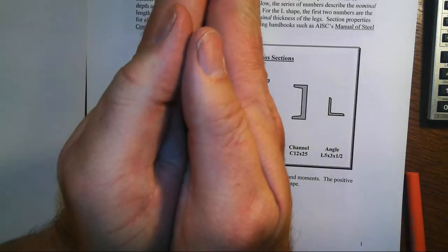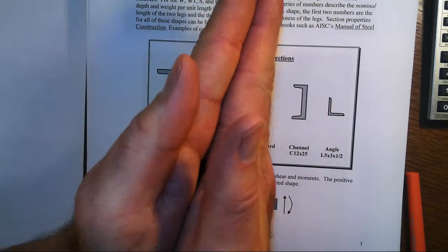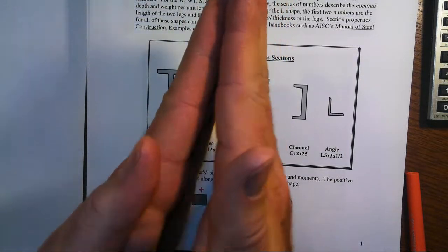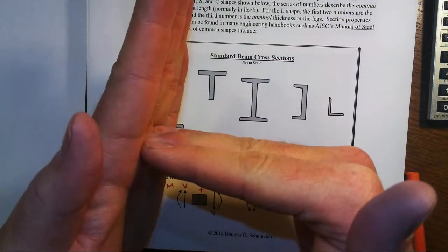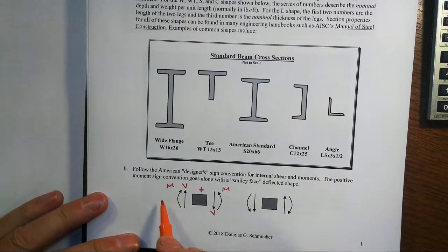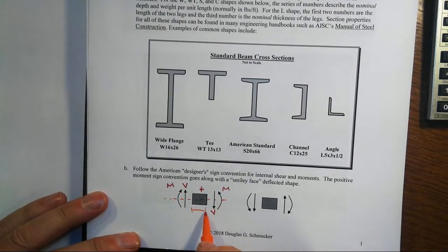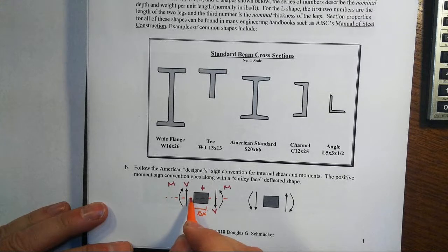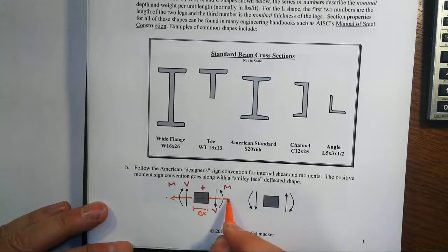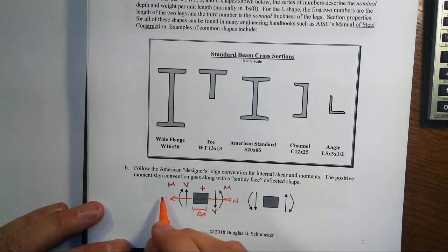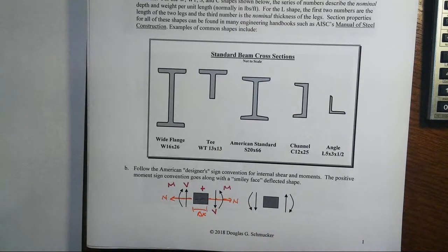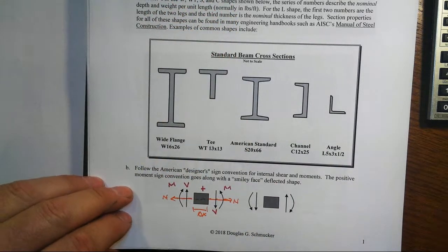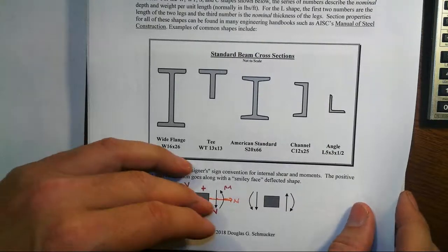Shearing would be, take your hands together and rub them back and forth. That's the shear plane. So shear is parallel to the surface, whereas normal is, of course, perpendicular to the surface. In this case, the longitudinal axis of this beam is horizontal. This is a little delta x or dx of the beam length, and so the axial forces that we've been looking at before, there you would have tension. That oftentimes is called positive, and compression is oftentimes called negative. Well, shear is the force that is parallel to that surface, almost like a sliding type of force.